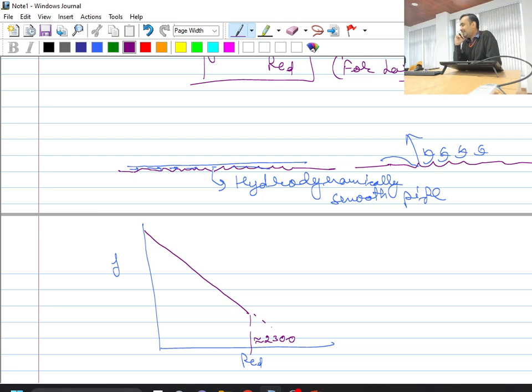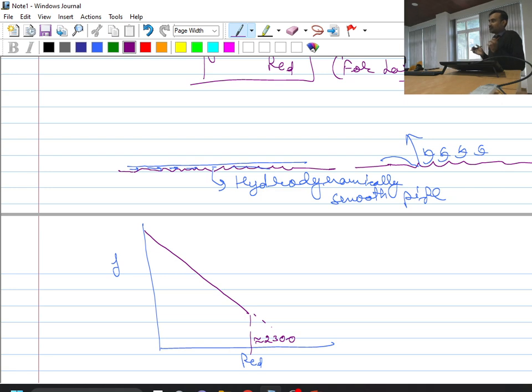So it means that up to the laminar flow conditions, the critical Reynolds number of 2300, we are able to develop a good understanding between the friction factor and the Reynolds number, and if the friction factor is known, then I can say we have a good understanding between the pressure drop and the velocity condition or Reynolds number.